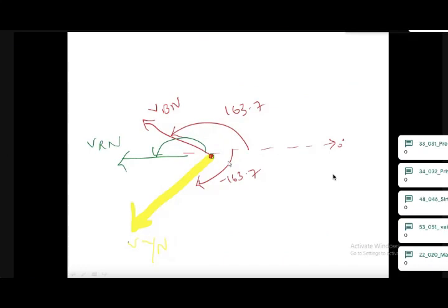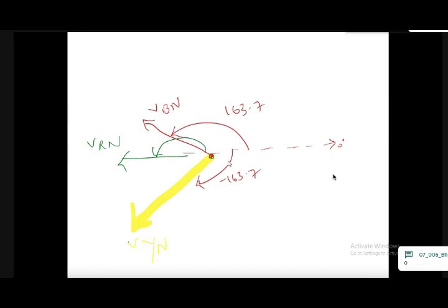VRN is what? The phase voltage on the load side. It is 371 in magnitude at an angle 180 degree with respect to the reference. The reference is 0 degree taken. And from 0, you have to measure 180 degrees and plot the value. That is VRN. Understood? Next, VYN I have to plot.